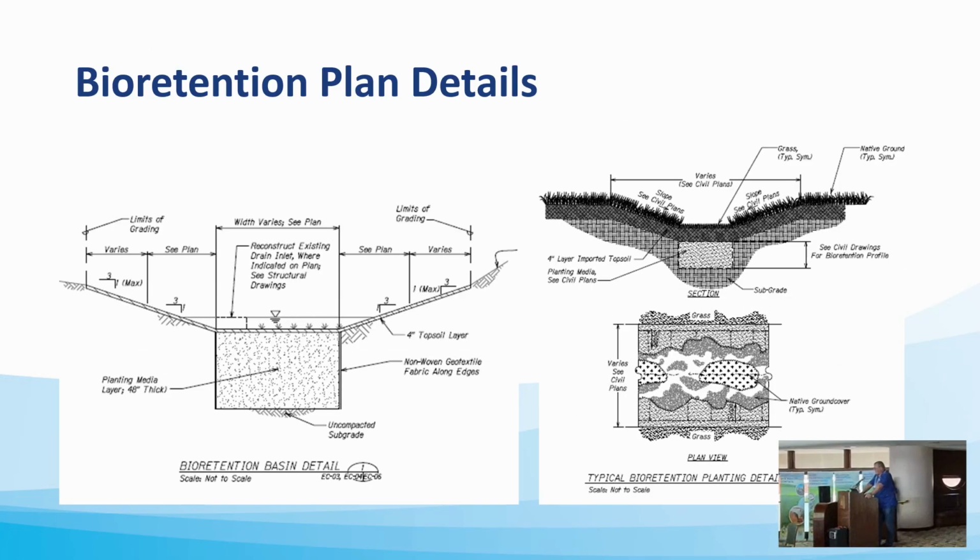Plan details. The site is relatively dry and soils have very high infiltration rates. The bioretention is designed with a 4-foot thick bioretention soil mix layer that provides infiltration into the native soil. The bioretention soil layer is designed to filter pollutants from stormwater, infiltrate the water into the ground, support healthy plant growth, and provide a medium for biological and chemical treatment processes that break down pollutants.